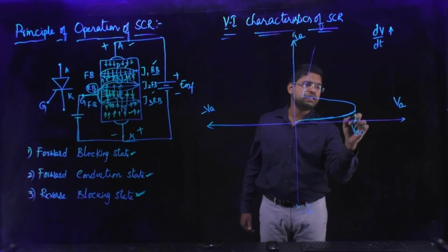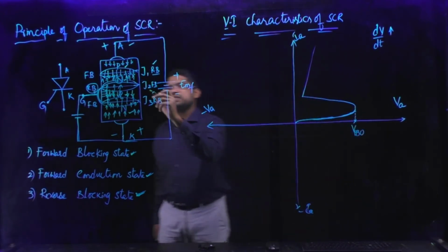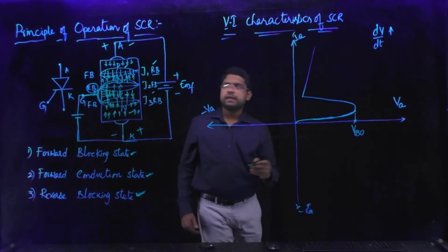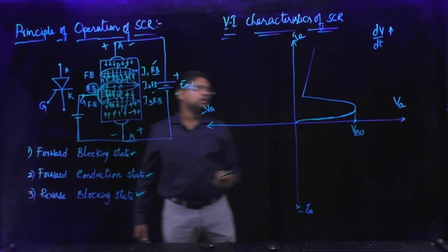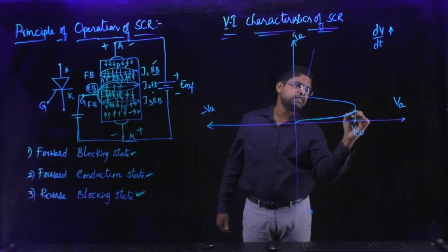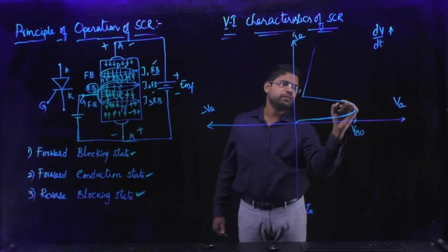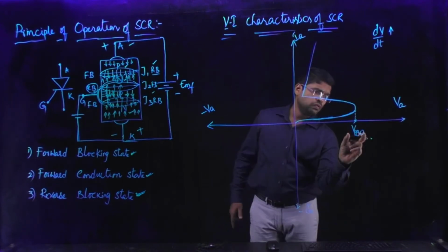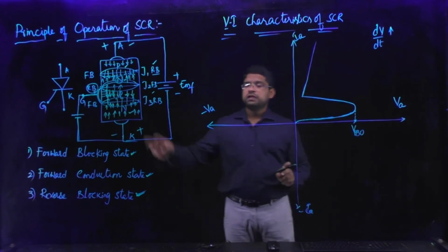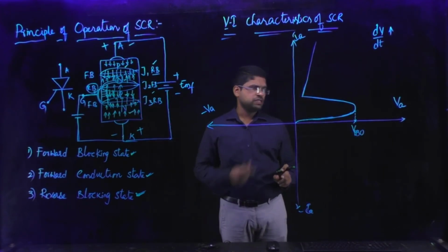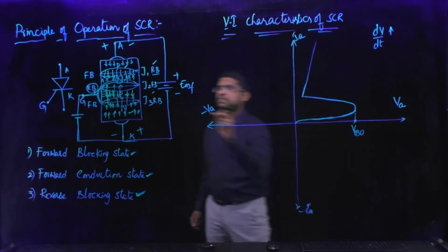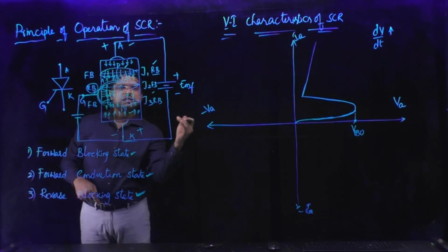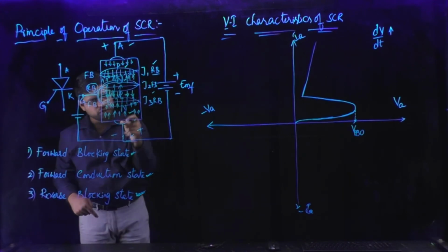When the depletion layer vanishes, the reverse bias at junction J2 is converted into forward bias and the device turns on. When the device turns on, the voltage across the device falls and the current through the device increases. With the help of avalanche breakdown voltage, the device is turned on during forward bias condition. As soon as the device is turned on, the device voltage suddenly falls and the current flowing through the device increases.